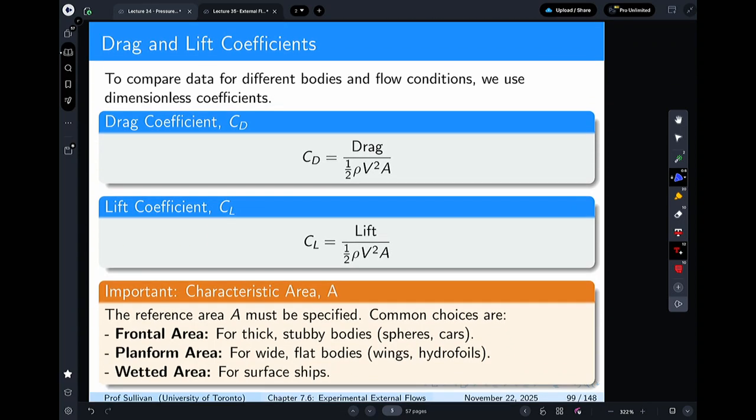Going back to chapter 5, you have C sub D, C sub L. Both of those are force dimensionless groups. C sub D deals with drag, C sub L deals with lift. And when you deal with airfoils, you're going to see a lot of images or charts where you have lift over drag, or lift versus angle of attack, various other things, Reynolds numbers. You also are going to have the same for C sub D, but you also have CL over CD charts.